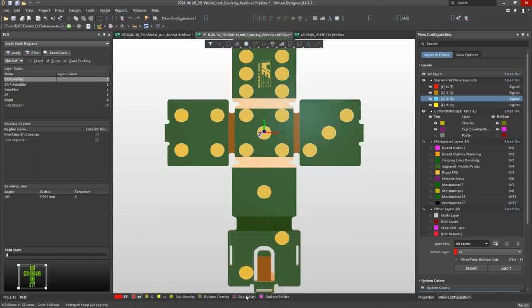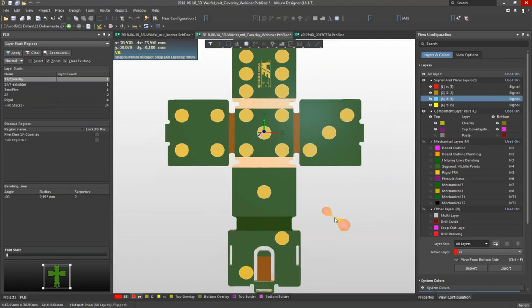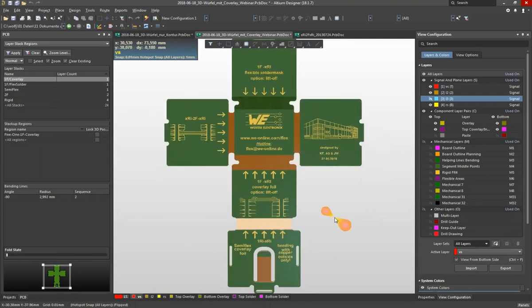So we switch, and you see the front layer basically just has the dots from the dice. And if we flip it, turn it around, you see on the back side we have the description of the different layers. And here you see very nicely that, for example, the 2F on the inner layer is being covered with coverlay. We have the difference for the two 1Fs.